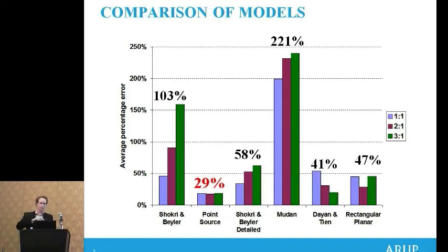I looked into that in some detail and found that one of the components of that model was calculating the average emissive power of the flame, and that was based on a correlation which was taken from quite a few tests, but mainly on a much larger scale, pool fires up to 10 metres in diameter, whereas my experimental program was on a much smaller scale. So I think that's where that model struggled, just the sheer scale of the experiments.